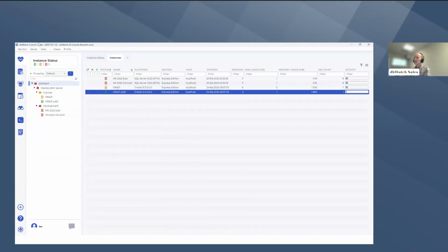To create a report, you have to go to the main menu, select Server, then select Reporting, and select the last menu, Create Report Template. And first, when you create a report template, you will have to add a name. So we'll call it Report 02.